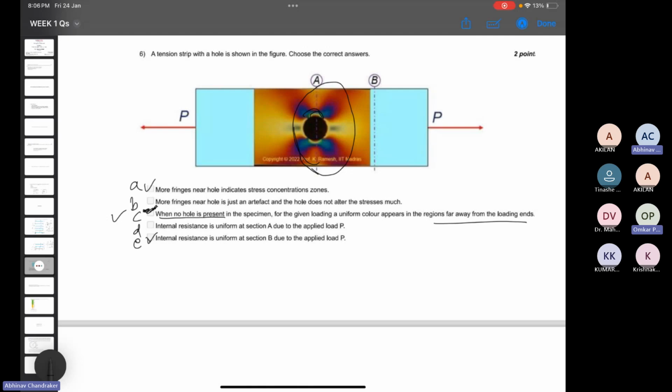And someone was asking related to bending, that in case of bending you will have stresses near the loading end. What I thought is they are speaking about a faraway region from the loading edge, the topmost and bottommost region. Okay, I see. Because it's being loaded locally as per this picture, right? Yes. But here we are assuming that the load is actually being applied on the whole surface. Else again we'll have stress concentration near this part. This is just for representation, but we are assuming that stress is being applied on the whole surface.